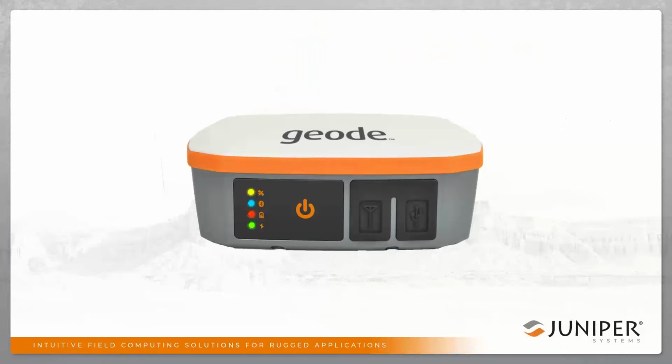Now, when you're mapping with the Mesa, it does have a built-in GPS, and with that built-in GPS, you'll get about a 2 to 5 meter accuracy, and that's not always good enough for what people need to do. And so we have the Geode, which is a sub-meter GPS receiver, and you pair that via Bluetooth to your tablet, and that acts as your location now.